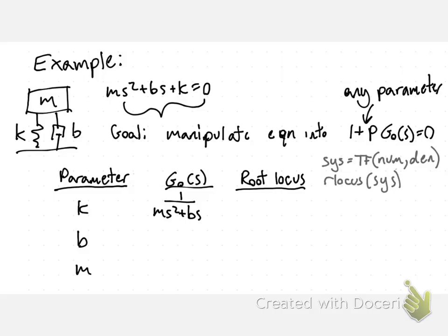And if we put that in the root locus format, the root locus always starts off at our open loop poles. So here we have a pole located at 0, and we have a pole located over here. And what happens is if we increase our k value, we're going to have two poles, and I'll draw them in different colors, but which one goes where doesn't really matter. MATLAB just likes doing two different colors to show what's happening with each of them.